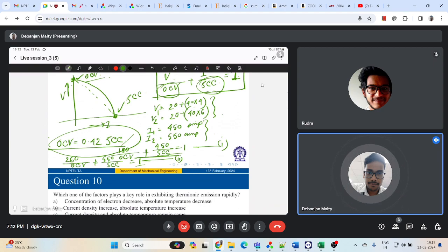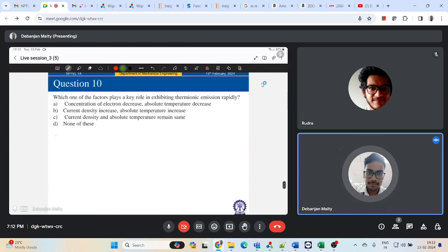The power units for short circuit or short arc welding usually incorporate an inductor in the output. The function of the inductor is that if there is any instantaneous change in voltage, the rise in current will be much slower.